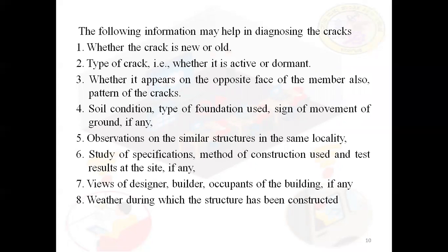The following information may help in diagnosing the cracks, whether the crack is new or old. By seeing the cracks, we can finalize whether the crack is old or new. Next, what is the type of crack, whether it is active or dormant? Next, whether it appears on the opposite face of the members also, and the pattern of the cracks.